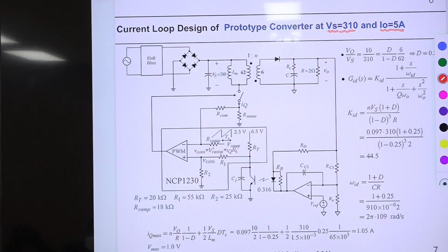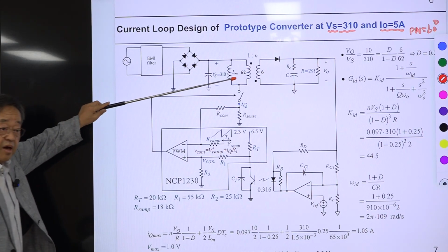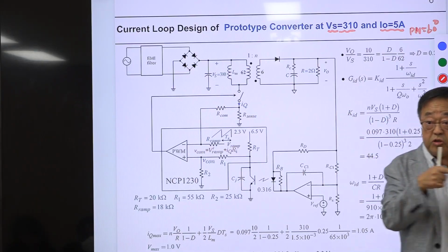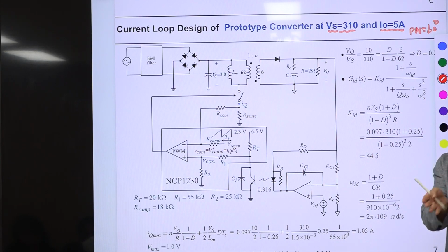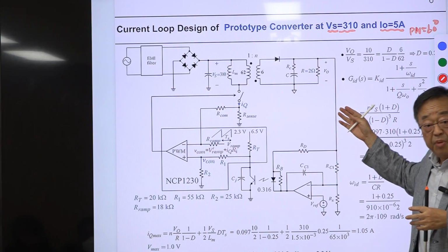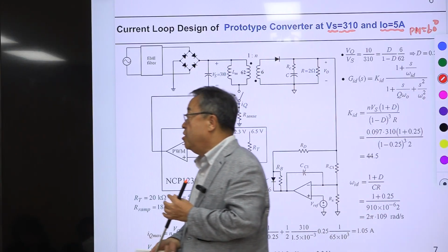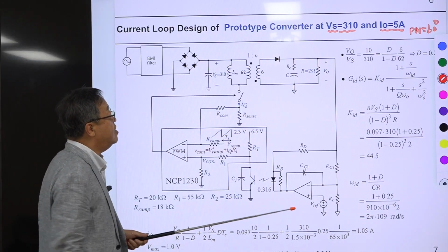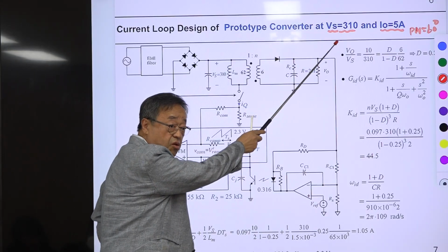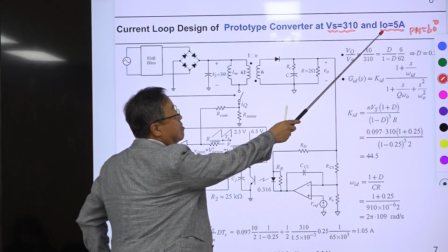So the phase margin, if it is something similar to 60 degrees, this design might be okay. I checked this out. This design is all good for the 4 corners, because of line and load: heavy load, low line, high line. So this is okay, but this is not the best choice. If you select your design again, you should select this Vs of 1 something, the low one, and the highest value of this.